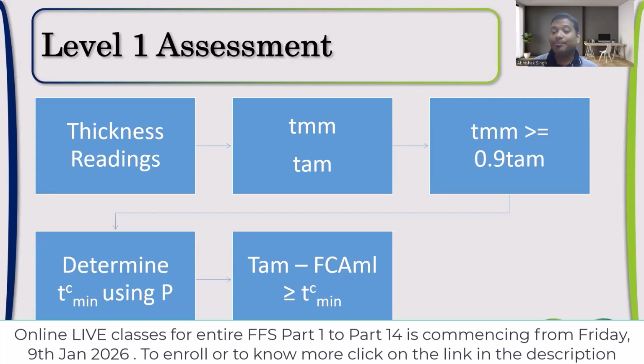To prevent that corrosion, like Sadhu discussed, externally it is very easy to prevent. Externally, it might have happened because of the loss of my coating or the paint. So if I'm able to remove it and do the painting properly and keep on monitoring that the painting is not damaged for some reason, I'm making sure that the corrosion rate is now limited. It is not going to be the same in the future.